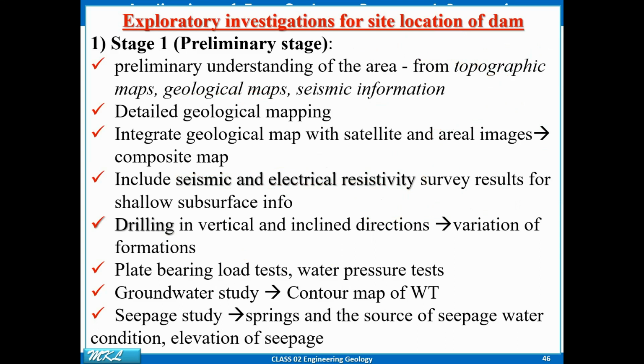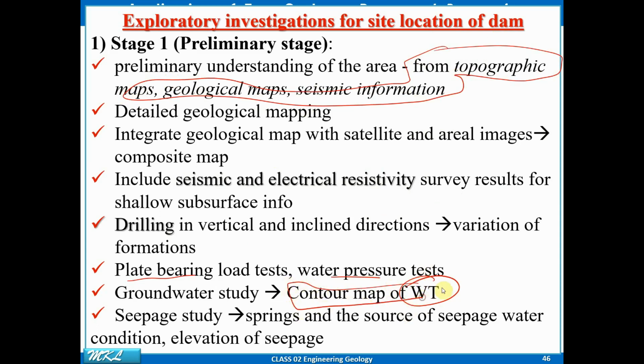There are other field-related engineering geological tests, like the plate bearing load test and the water pressure test, that you will be doing. Another most important thing you should consider along with this is any water table map available in that area. If there is a water contour map available in that area, then it is okay.